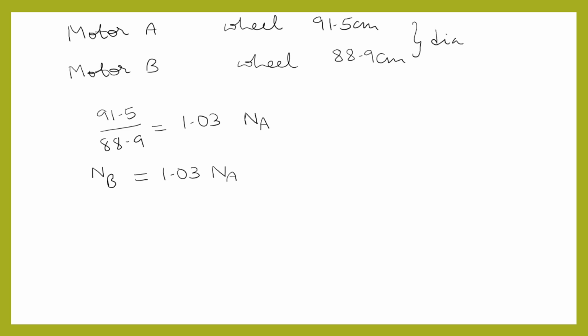So we can conclude that the motors are fairly equally loaded. Though the division of load is there between the two motors, seeing the speed time curve, there is not much difference between the current drawn by the two motors. Therefore, we can conclude that the two motors are fairly equally loaded.